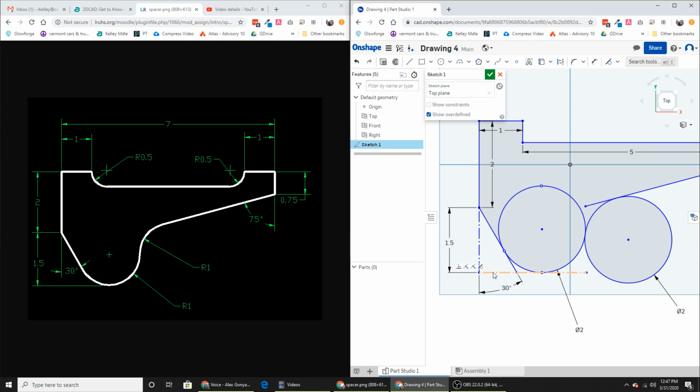Alright, these construction lines, we probably don't need them all. So, I'm going to select that one, delete, goes away, select this one, delete, it goes away. Now this line is too long, there's too much of this circle here. We only need this bottom part. The whole top part can be trimmed away. There's too much of this circle. We need to trim all of this away. This line is a little too long. So let's get busy trimming things up.